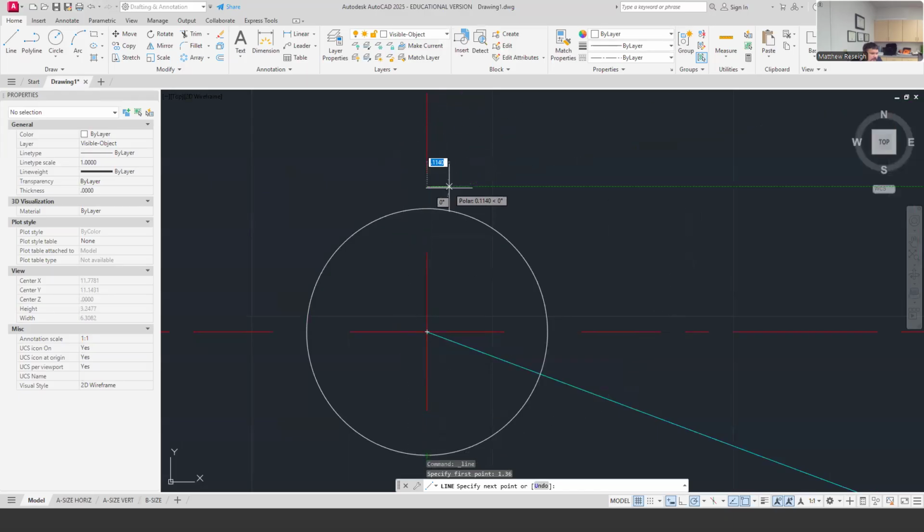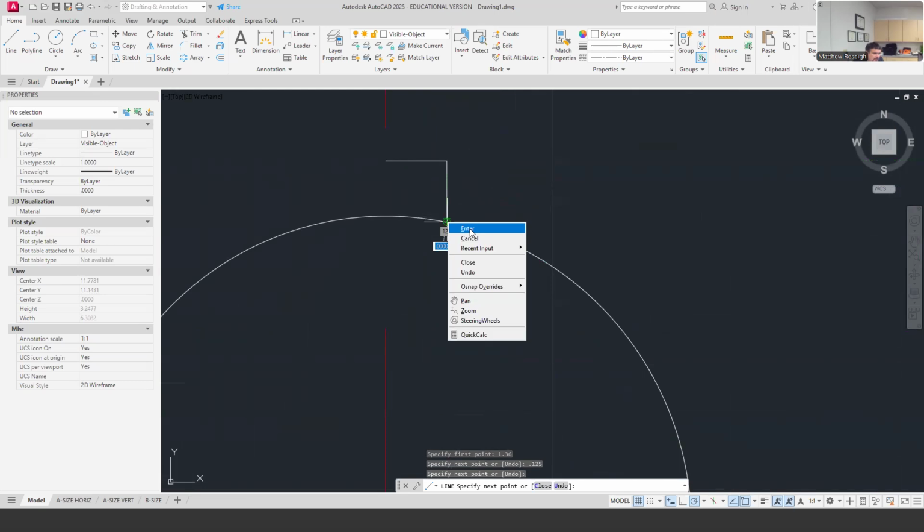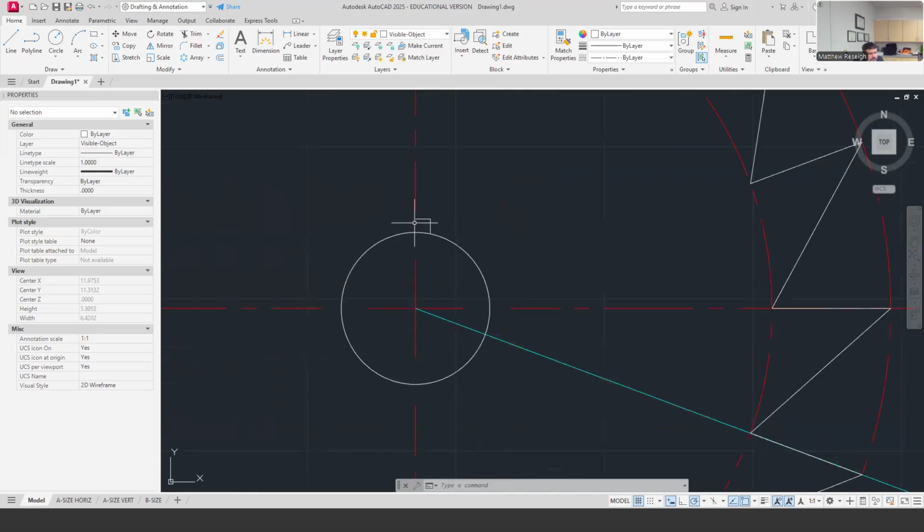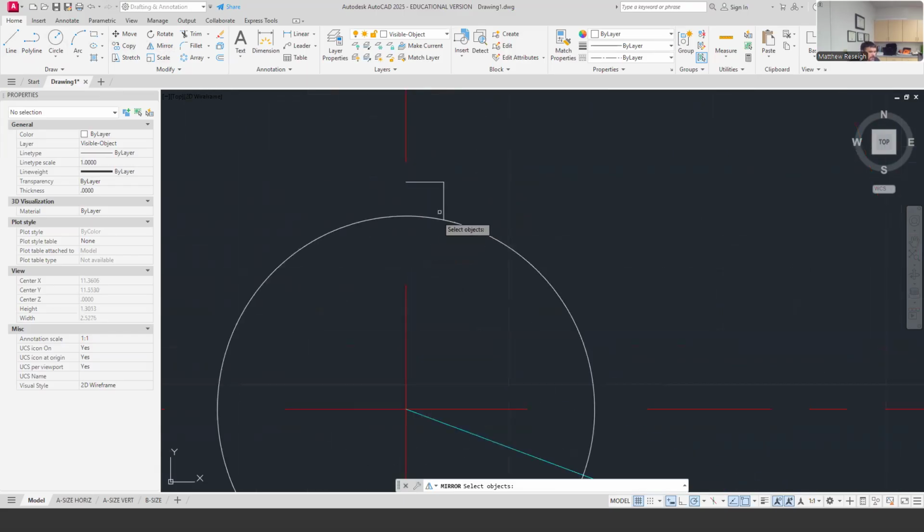I just cursored up. Now I'm going to drive this over 0.125 and then straight back down to where it hits that key there like that. That's just half the keyway there. So I used 1.36 up, over 1/8 of an inch, down, and I'm just going to mirror those two parts over, and maybe I'll join them. If I get into my mirror command correctly, those two along the center. No. I might just join these. Might trim this first, though. I'm going to trim out this.